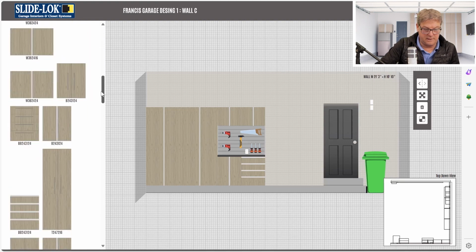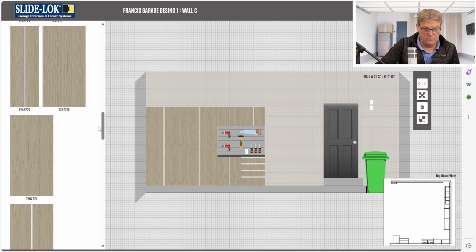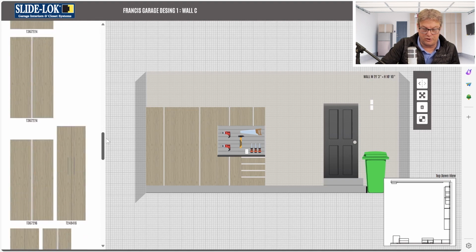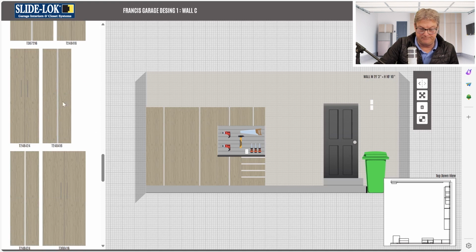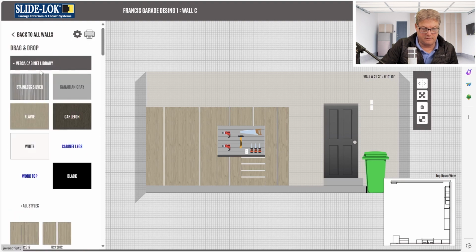And then we're going to add the last anchor cabinet, which the client is also going to be using for shoes by the door. So again, with shoe cabinets, you only need them at 16-inch deep. Again, we're off the floor. That's the stem wall. It's going to sit on the back of the stem wall. You can put this at any height you want. Our cabinets do not use feet. Each wall we're going to save.